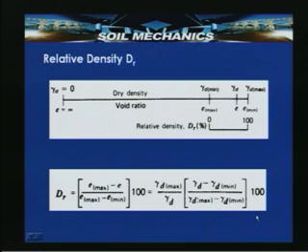So, if you know the maximum void ratio and minimum void ratio of a given soil which is being used for filling or compacting in a particular area, and by knowing the in situ void ratio, we will be able to determine the compactness or the degree of compaction at a particular time.